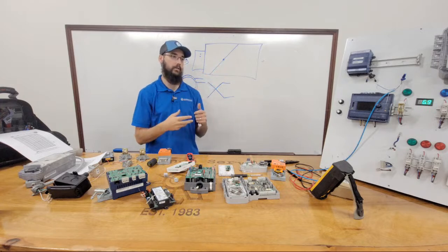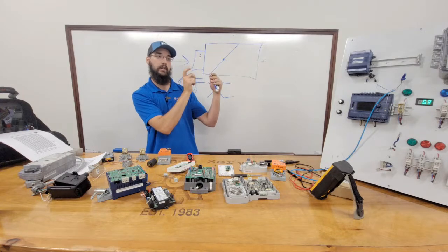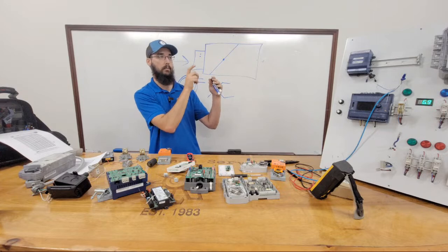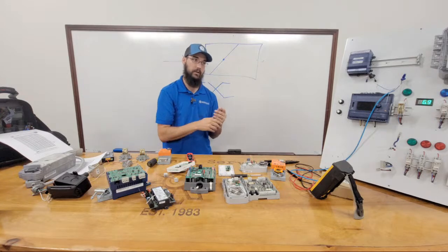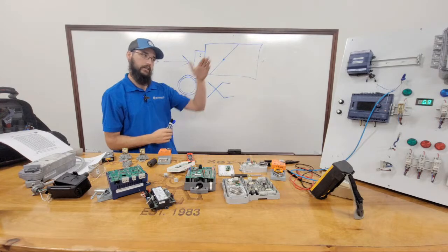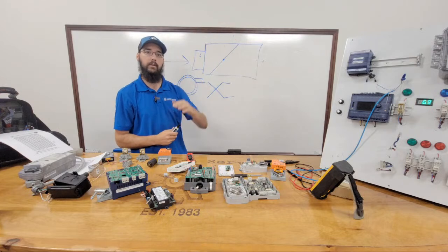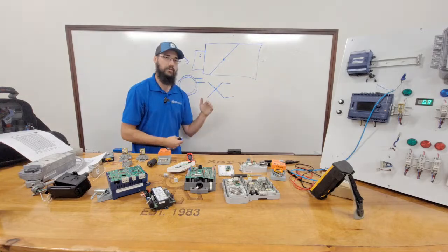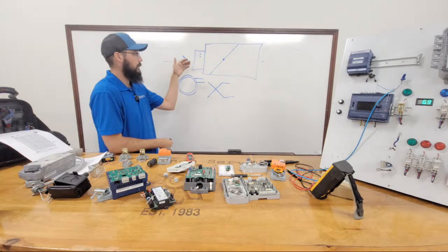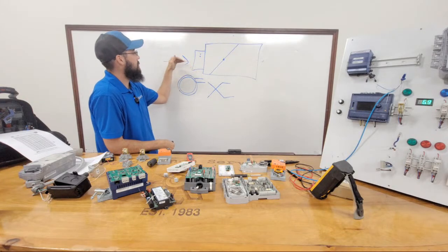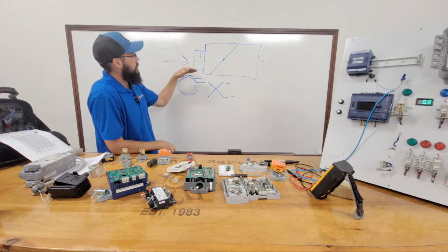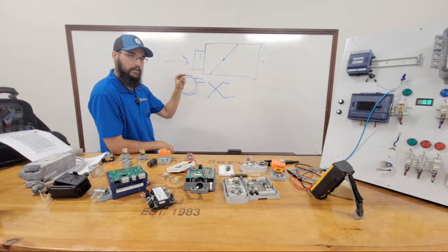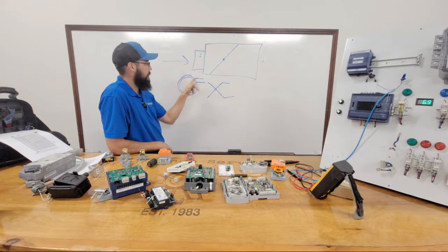And a lot of your VAVs or fan powers, you'll see this little weird looking kind of bar, or not bar, but line graph on there. It looks typically pretty strange. And it'll have like just a straight line across with CFM and 8-inch, 10-inch, whatever sizes. That is your flow chart for the box. And those are pretty universal. How we're getting the reading to read that graph is through this.